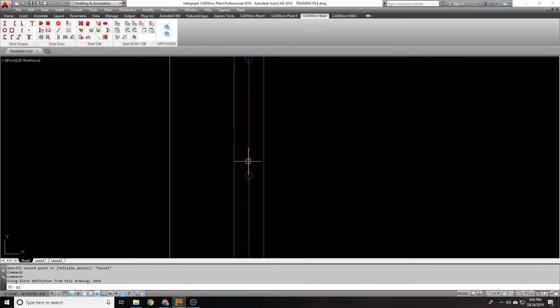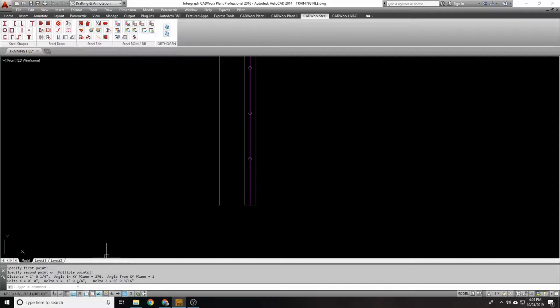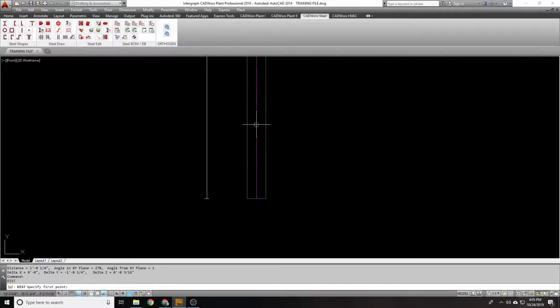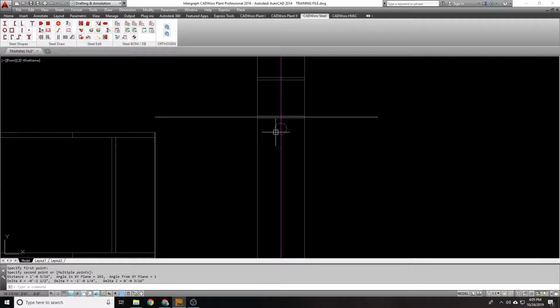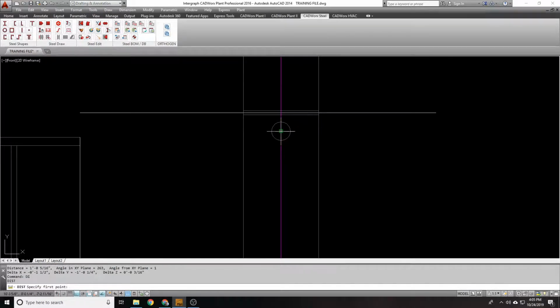It's probably getting them from the bottom. See, 1 1/4, or yeah, 1 1/4. It's getting it from the bottom. So, all right, I know it's confusing, but bottom line, if you want this by default, the center line of this top rung is always 3/4 of an inch below what you set the height at. So just remember that, 3/4 of an inch below.